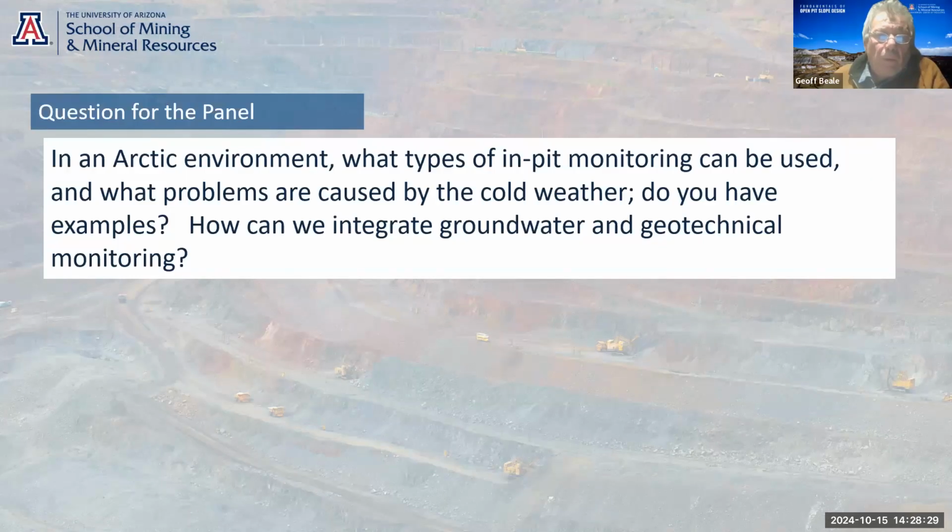One of the things we found in a number of Arctic sites, and Diavik is one of them, is freeze back in the pit slopes. So we've had piezometers close behind the pit walls, which show declining temperatures at the point where the slope starts to freeze again, particularly north and east facing slopes. Just knowing that can be important for the geotech analysis as well, because obviously if it freezes, then the strength will increase. So the great thing about the piezometers is you can measure both temperatures and pressures.